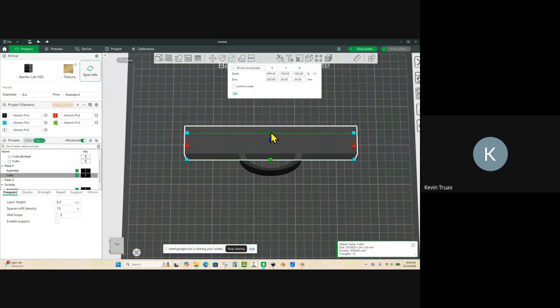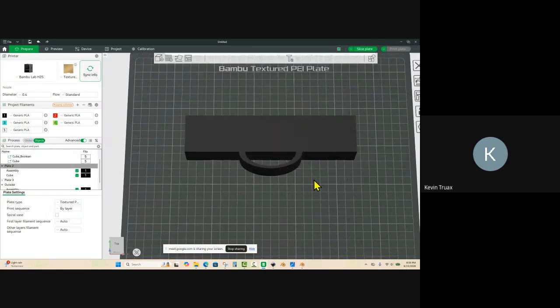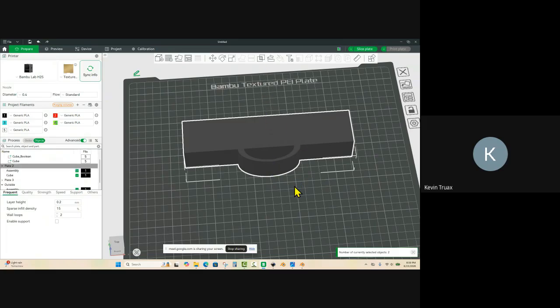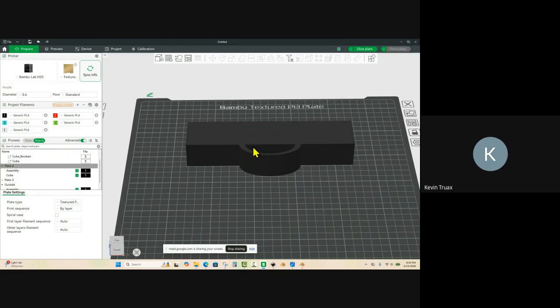We'll scale it back just this direction, and we're going to whack that off there. But we're going to control click both of these. When we do a Mesh Boolean, we need two pieces selected, but they don't necessarily have to be in an assembly to do it.